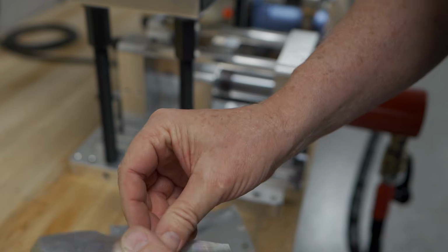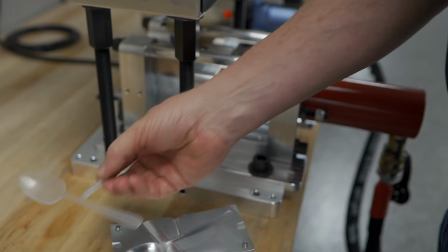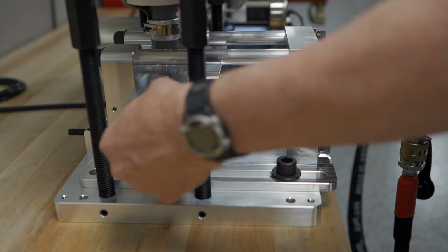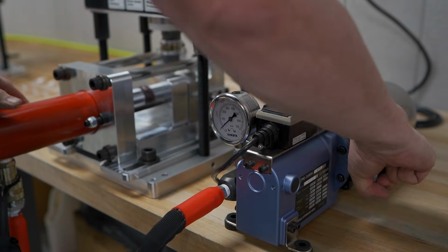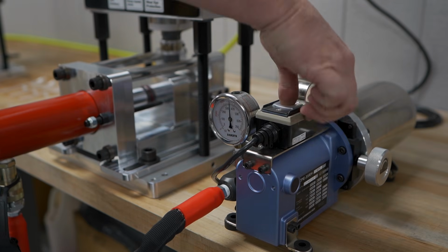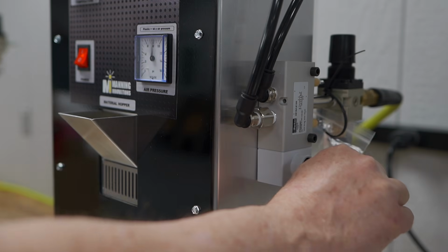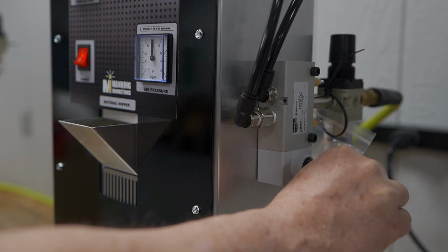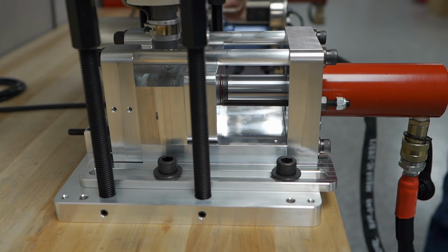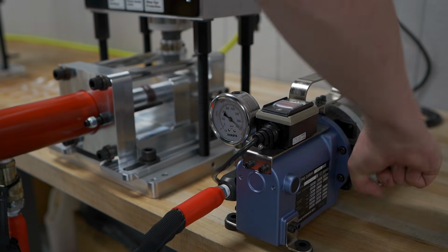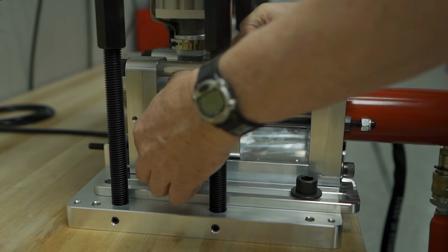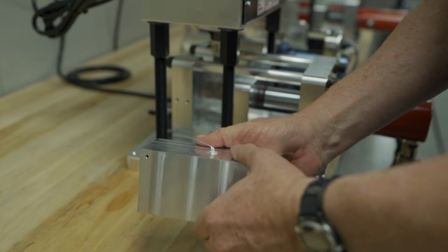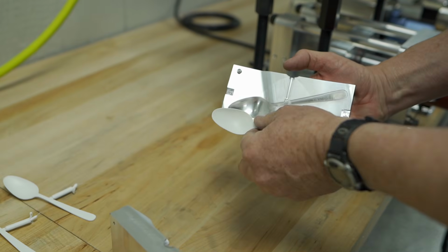It's stuck on the other side, kind of. I mean, it doesn't really stick at all. This doesn't really have anything that grabs onto the parts. Here's another view that allows you to see where he's closing the clamp. Then he turns on the pump, injects. You can see the hopper move down with the cylinder. And then release the pressure. You can see the cylinder moved up, release the hydraulic pressure, and then you can take the mold out. And again, you're going to see just how easily the part falls out. So it's not really grabbing onto anything.